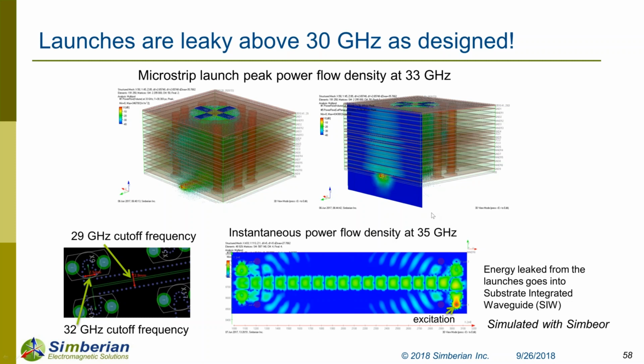That will require some rethinking about how to make the PCB interconnect. If somebody just insists that they used to do it like this, like power signal ground, or use just one stitching via per some number of signal vias, they are not going to survive in this.